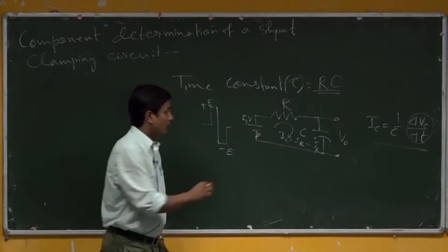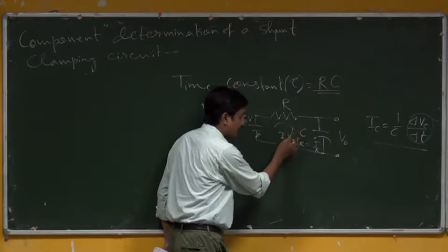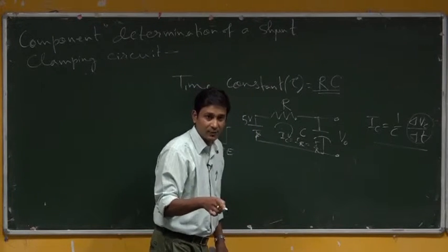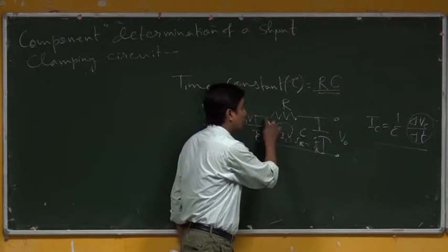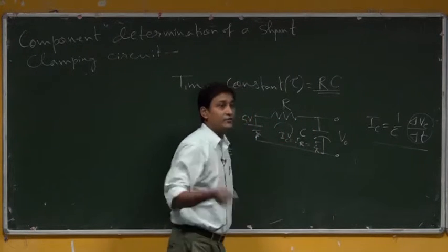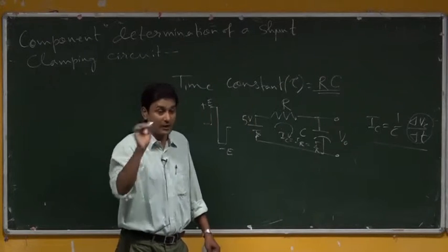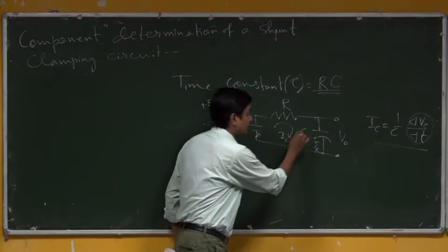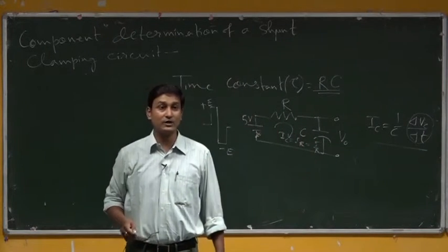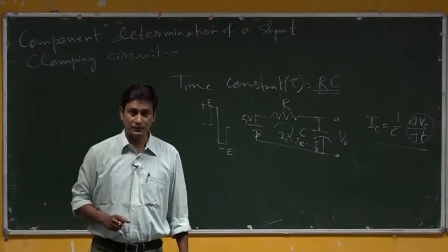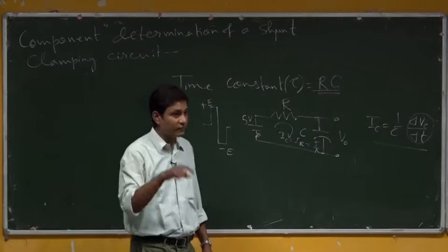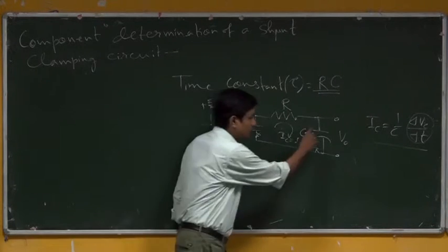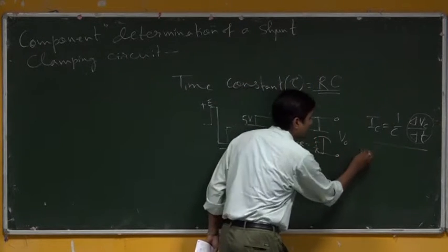Now, some non-zero current is flowing, at its highest value I will say, because the potential here is 0. So, the current flowing through the circuitry is fully decided by the resistor itself, as if the capacitor is not at all there. But immediately after current flows through the capacitor, the capacitor will start charging. So, current is the cause for developing potential across the capacitor. Whenever some current flows, some potential will get developed here, say 1 volt after some time.